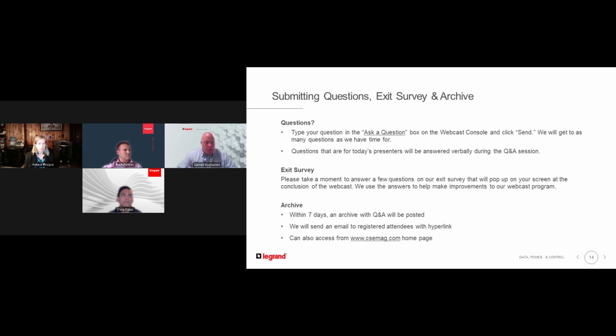Yeah, great question. If we're talking about data center power distribution, the difference is typically the ampacity limitation on the open channel or Starline style busway systems. As I previously mentioned, our system does go up to 1200 amps, and all of those systems are continuous access, meaning that you can place one of our plug-in units anywhere along that open channel, along the entire length of the bus. Anything exceeding 1200 amps currently we're seeing move toward the typical sandwich style bus duct system. So right now we're really just seeing that sandwich style deployed where higher ampacities are required.